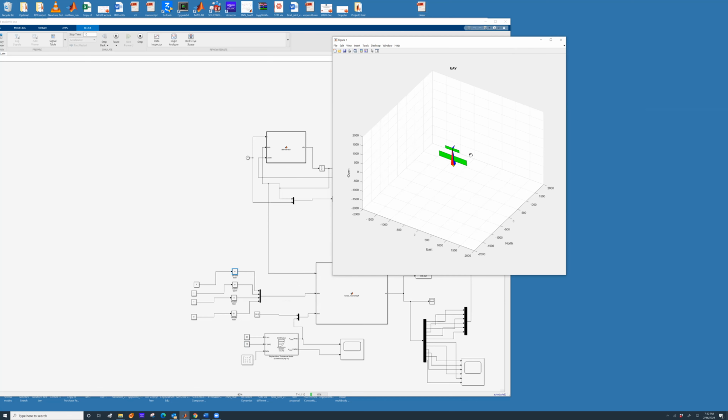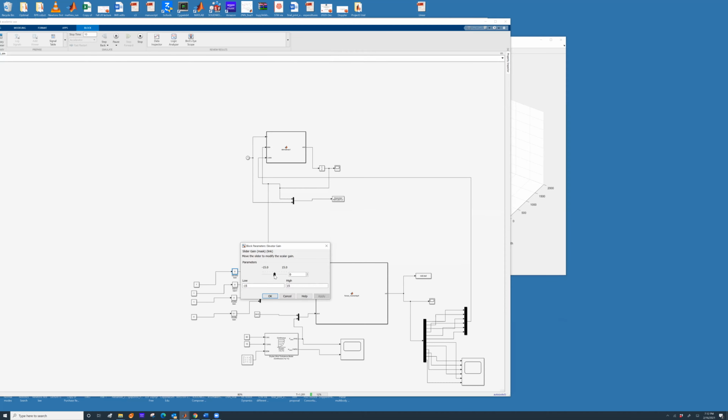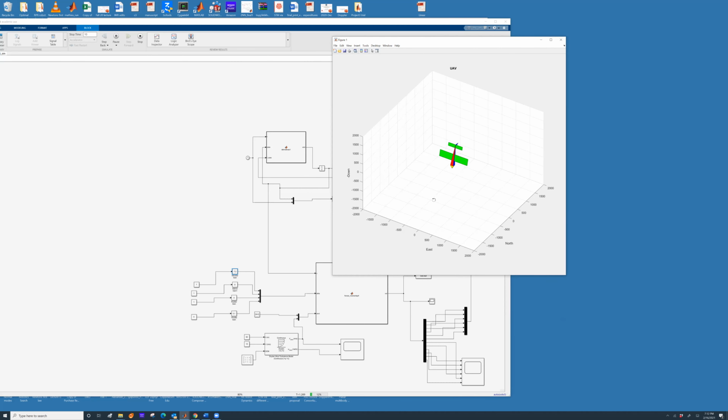Once again, the values that this airframe is using are for Aerosonde. That is not right. So to make your simulation run properly, you will have to use the airframe values for Zagi. Now you see I changed the elevator gain and the aircraft is back into level flight.